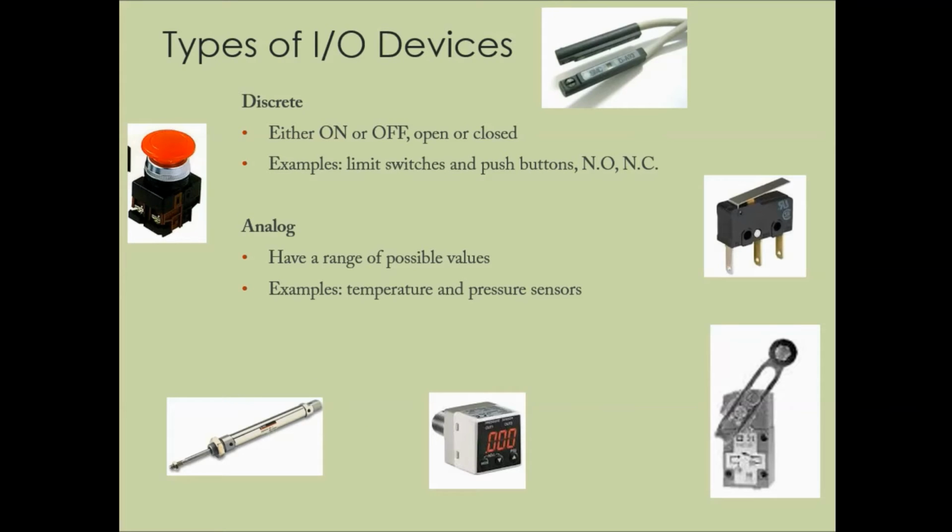Types of I/O devices. We have discrete, either on or off, open or closed. It's going to give you a 1 or a 0 as a logic level. Examples of this are limit switches and push buttons, normally open, normally closed.